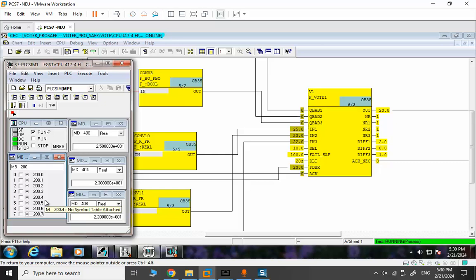And the final case, for final function tests, we have two bad quality signals. So as an example, consider input 3 and input 2. If we have two bad quality signals, shut down immediately, and everything is getting normal after the quality is returning to the normal case.